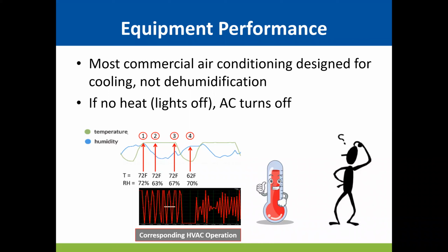And then the lights turn off. Well, there's no heat gain to the room. So your thermostat's like, hey, I'm cool, right? Literally, I'm cool. I don't need to do any work. And your air conditioner turns off because the temperature is fine. And you're like, oh no, what just happened? Why is my humidity spiking at night? Because your air conditioner turned off, right?